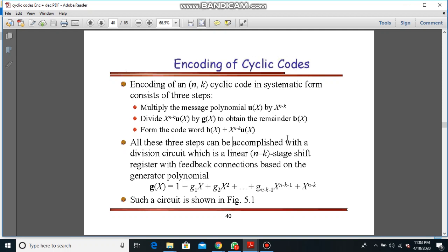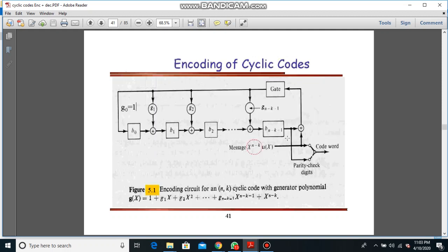So you will see the encoder designed for cyclic code. This is the design of the encoder. What we are doing here is a very simple block diagram; for any order (n, k) you can design it. Clear? So how do I start? This is my code word. I will give the code word, and it will go to this modulo 2 operator. One gate is there.